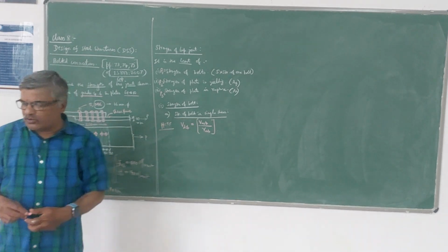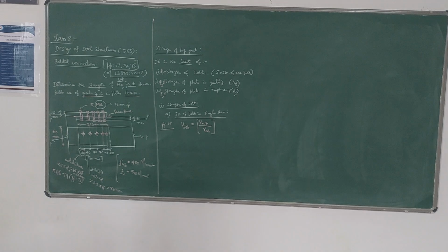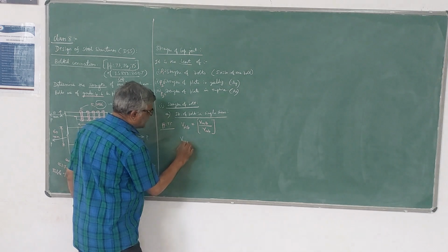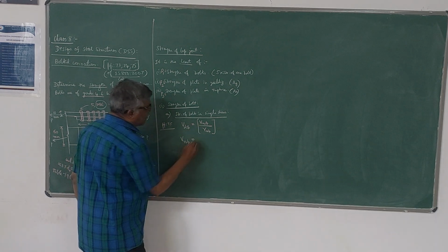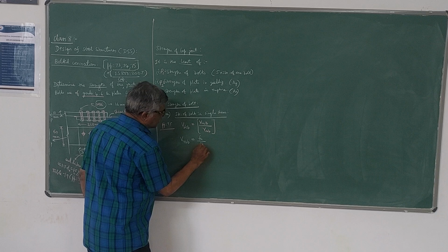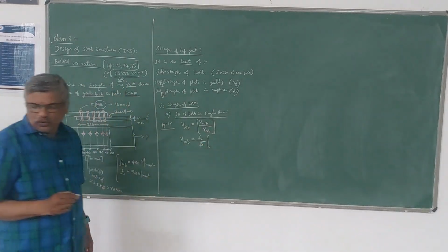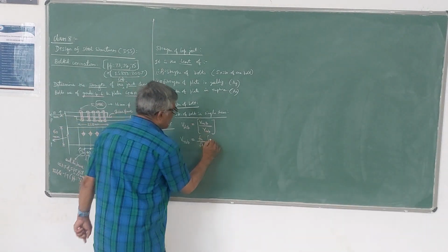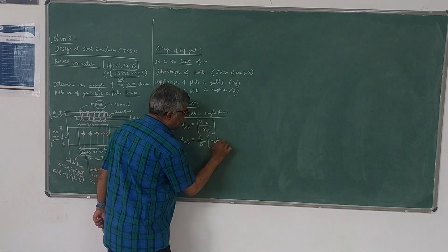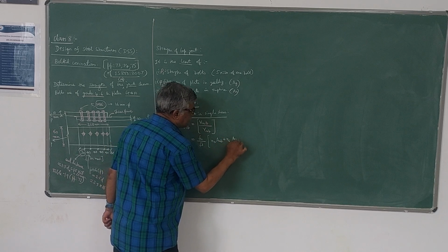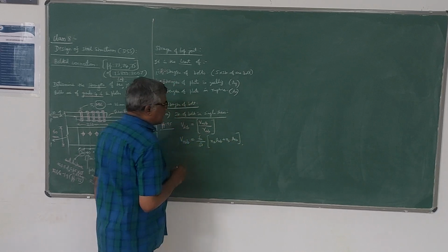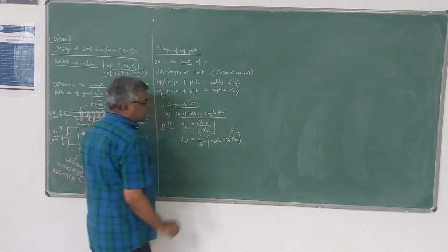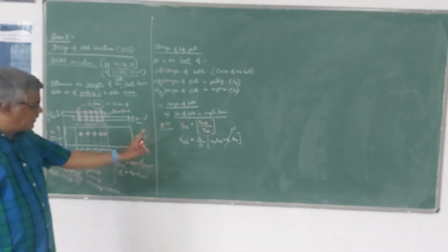Now there is a formula to find VNSB. It is given there. VNSB is equal to FU by root 3 into, you have two terms in the brackets, NN ANB plus NS ASB. Everything is explained in the code. You need not memorize any formula. In the case of single shear, there is only one shear plane, so the NS value will be 0 and the NN value will be 1.